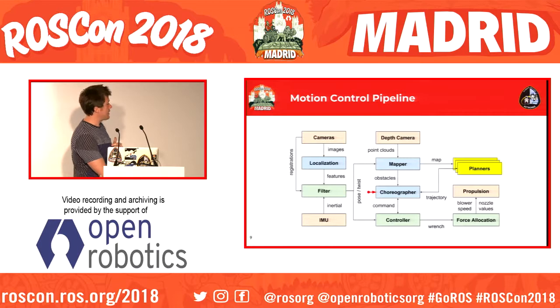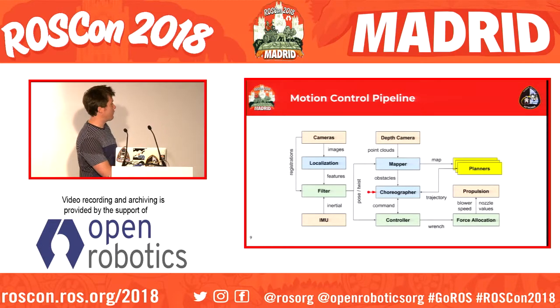Now the controller is, I believe, a relatively simple PID controller. The command would be a segment or a trajectory you want to follow, and then you get the output of your filter, and the controller works out what wrench you want to achieve, so standard sort of control stuff. The filter, which is our state estimator, our guidance navigation system, takes IMU measurements, propagates them forward, and then periodically corrects them with features.